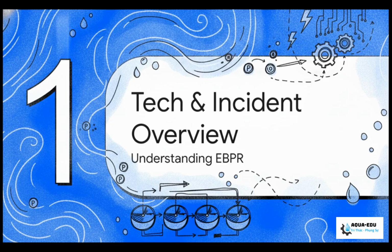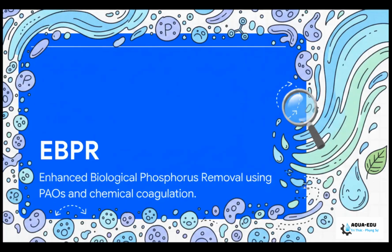First things first, brothers. Before we can fix a broken system, we've got to ground ourselves in the actual science of how these systems remove phosphorus in the first place. Now, your absolute primary weapon against phosphorus is EBPR, or Enhanced Biological Phosphorus Removal. This entire technology hinges completely on the life cycle of your PAO bacteria, that's polyphosphate accumulating organisms. These microscopic little workers literally do the heavy lifting for you, sometimes with a little backup from chemical coagulation. Protecting their very specific environment, that's your #1 priority on the floor. Bottom line, if the PAOs are happy, your effluent is clean.